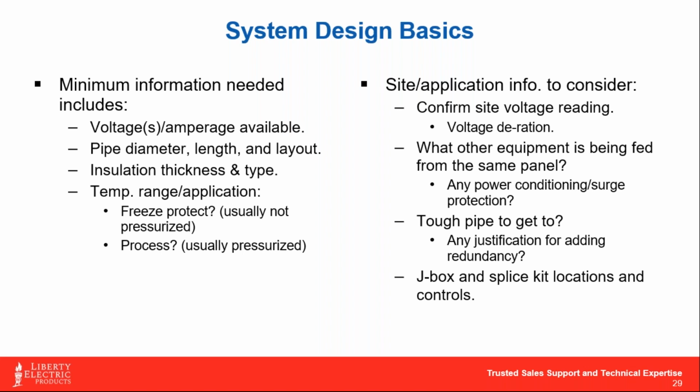Here's a perfect example of making the comparison of what it's going to cost for me to grab a backhoe in 15 years, dig up the parking lot, open up that trench, expose the pipe, take off the heat trace cable and the insulation, put on a new line of, 40 foot, mind you, of heat trace cable on this thing, rewrap it with insulation, fill back in your hole and call it a day. The heat trace cable is going to cost you $1,500. The rest of the project's going to cost you 30 grand. So where we look for these types of applications is where you know that over time, replacing this is going to be a big headache.